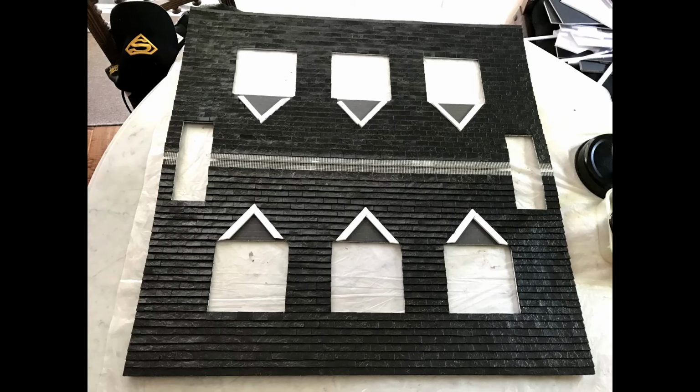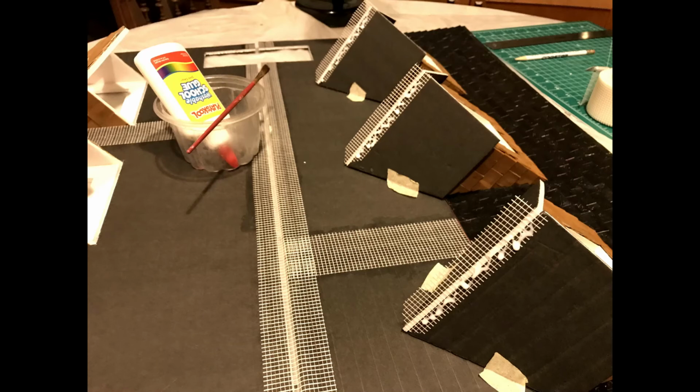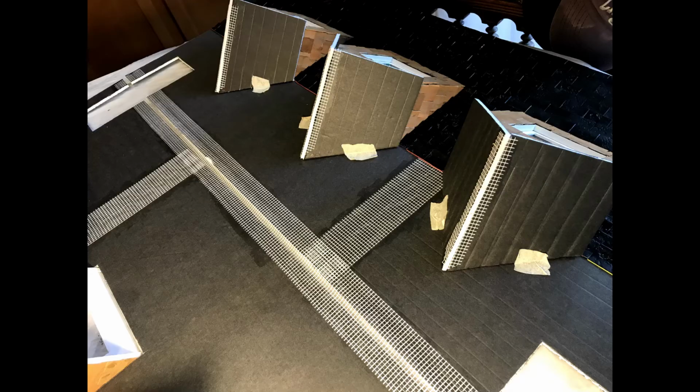For each dormer roof, I installed a small support to mirror the front facade of the dormer. This made the structure more secure and kept the alignment in the correct location. This also let me know where to stop the roof shingling for the house roof. One side of the dormer roof is slightly longer than the other side and overlaps the other panel to form the peak. The drywall tape was glued to the joint to maintain the orientation of the panels.